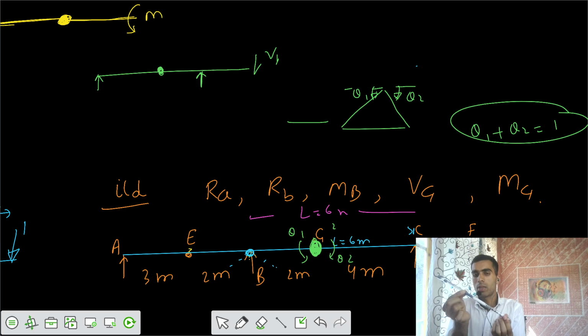If there is no curvature developed, and I can have point A at its original location, that means there should be use of an internal hinge somewhere. So I got this profile now. Point B is at its original location, but point G has gone upwards, and your hinge has gone down with respect to point B, and support A is at the level of B. So this is your profile. That means this is possible. There is no curvature developed, so theta 1 would be there.